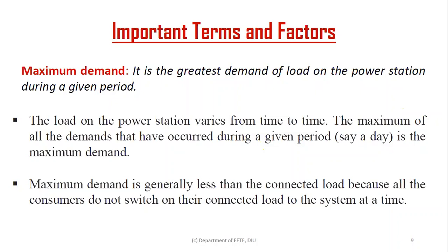So remember one thing: individual maximum demand does not happen at the same time, because I have my maximum demand at my own time. Probably Abdi Aziz has his own time, the shopping mall has its own time, the school has its own time, and the mosque has its own time, five times a day, when all the loads are on.